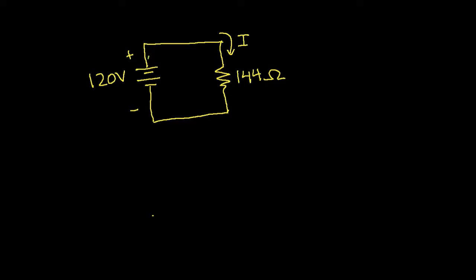So the first is this. This part of the wire that I'm outlining in green is all part of one node in the circuit. A node is defined to be basically everything that's connected by just a wire. Because we assume wires are perfectly conducting, there's no voltage difference between any 2 points along this wire. So there's no voltage drop between here and here.